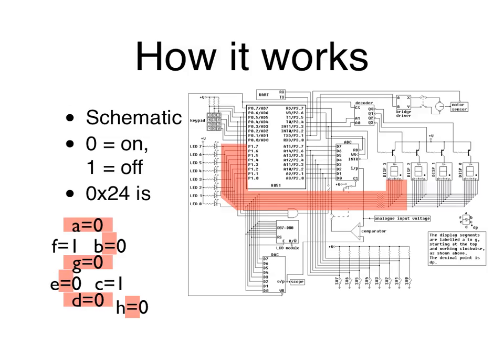So this is something I think software people have to get used to. There are reasons for connecting things backwards. That's because your general purpose I/O pins are not really meant for supplying power. They're just signals. Their purpose is to provide a digital value, not necessarily to drive or to turn on. Not enough power to power the light. And each LED segment consumes quite a bit of power compared to what the microcontroller can do.